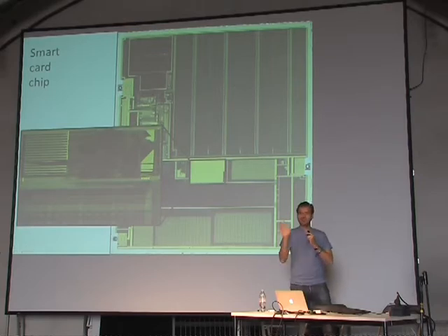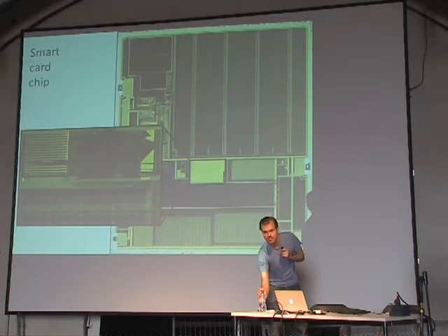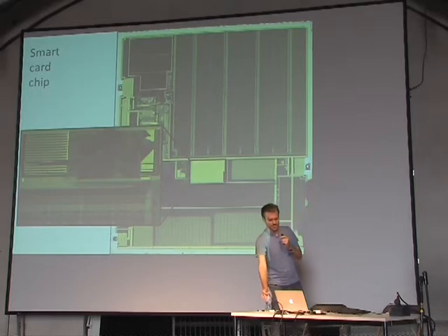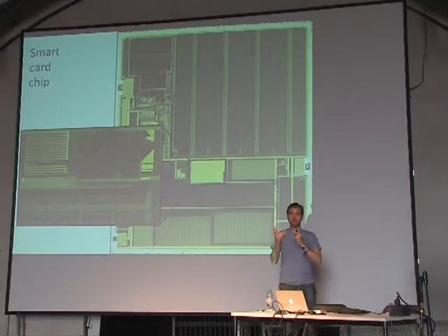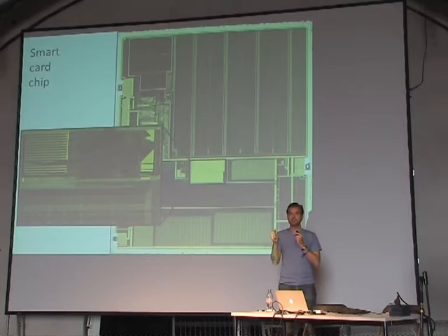So usually people don't yet use flash-only chips. However, one exists at least. But I don't think that's being implemented for a security purpose, but they can be used for different purposes. I mean, it's just a stock management thing. I like flash-only chips. If you can limit your application footprint to maybe the 72K that this chip already has, just don't use the ROM. Do in the ROM a jump to flash immediately, which allows you first to stay out of this type of analysis, which I don't think would be the security argument, but it will allow you to update your software in the field if you do find a bug, right?